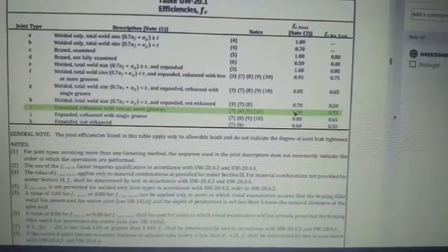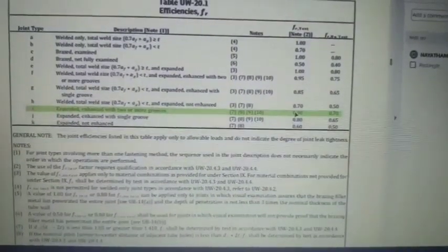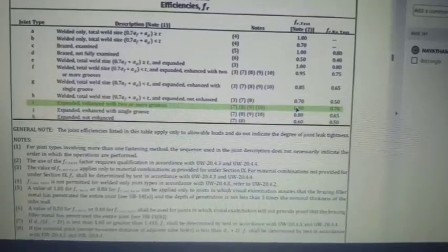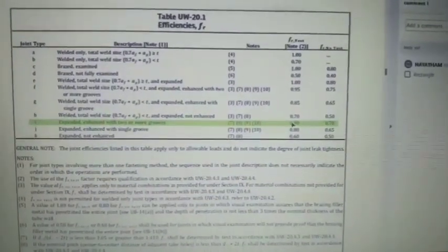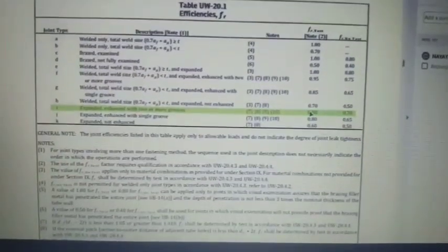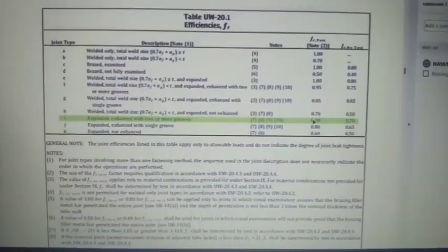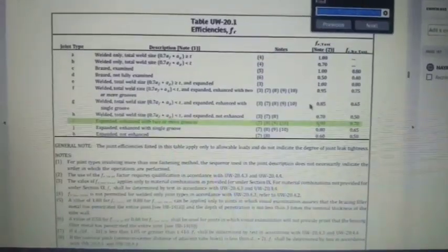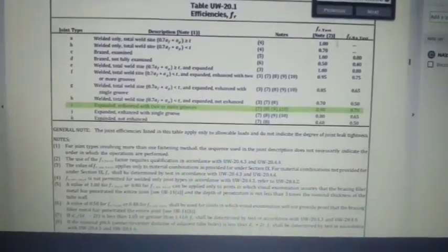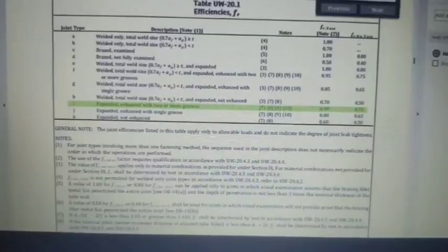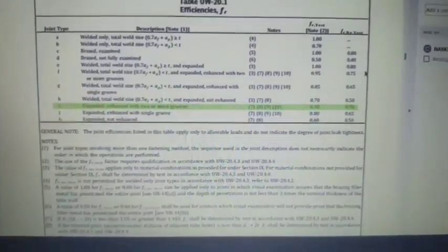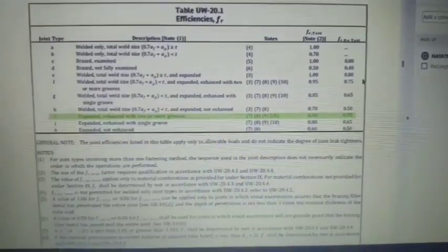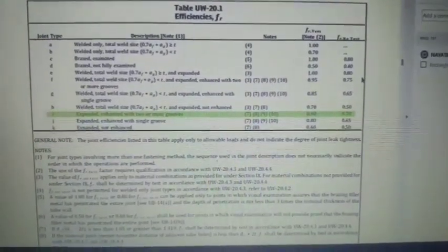You mean full strength joint? You were talking about an expanded joint with two grooves, fully expanded, okay? You mean full strength? Yes. But just find out what this FR test is, how it will be done. They will put some load, no? I think that is a pull-out load. So just see how that pull-out load test is done. Probably you should get a hint.